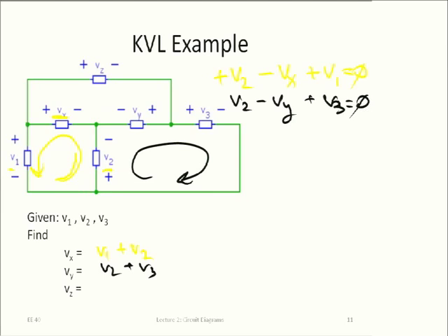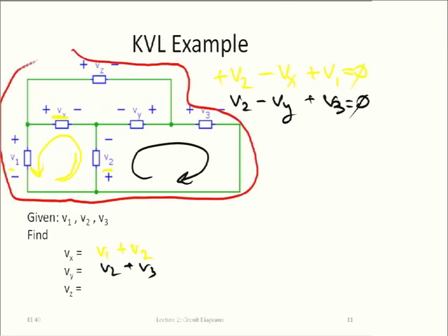Well, now we could make another loop for Vc that goes here, here, and here, for example. Then we go through all the voltages that we actually know. Of course, we could also have chosen a different loop, like this one here. That would have been fine too, but then we would have to first solve for Vx and Vy, which would have been very difficult. In principle, we get 3 equations, 3 unknowns in this circuit, and we would have to solve them. But here we can do it cleverly, so we don't have to solve it all.